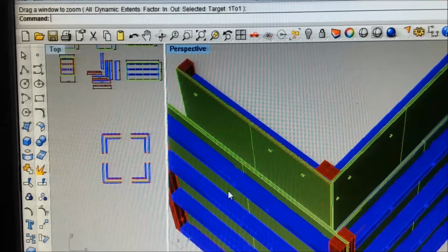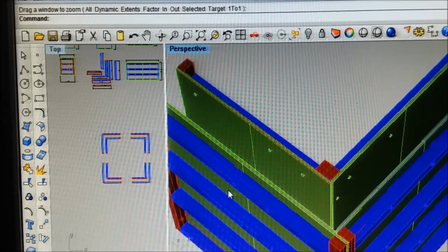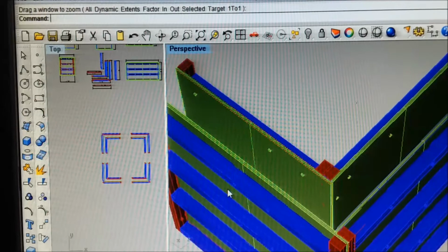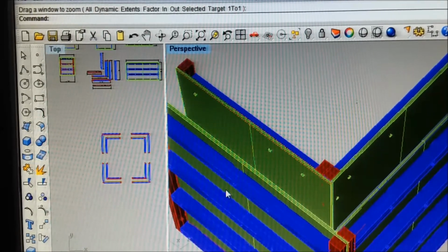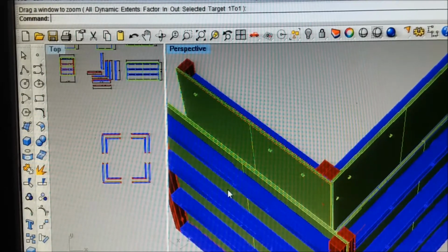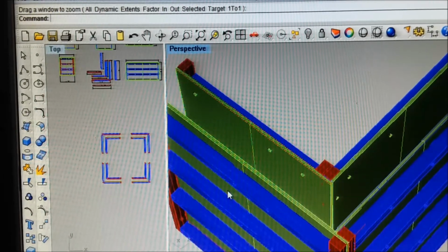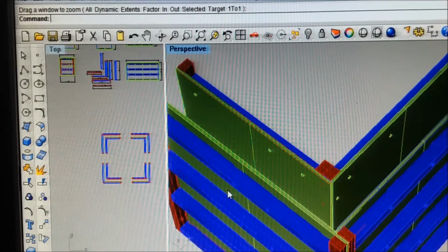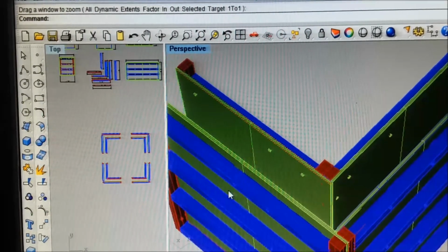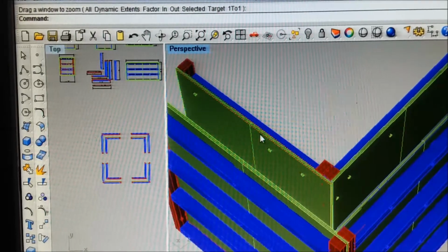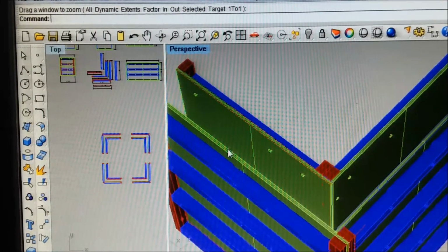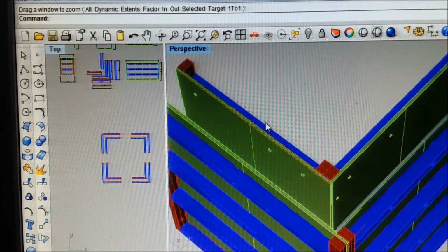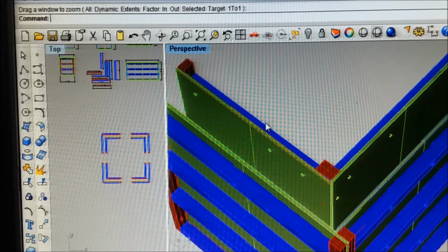Use no threaded rod thinner than 3/8. I would be uncomfortable with 3/8 because it puts enough strain on it that sometimes the threads upset a little bit, and it's a real miserable thing to get back apart. We use 1/2 inch. It's overkill. You could use 7/16 just fine, but try to find 7/16 rod or bolts that are this long, because you've got 7, 8 1/4, 11 1/4, 14 1/4 of stuff to go through, plus a washer and a nut on each side.